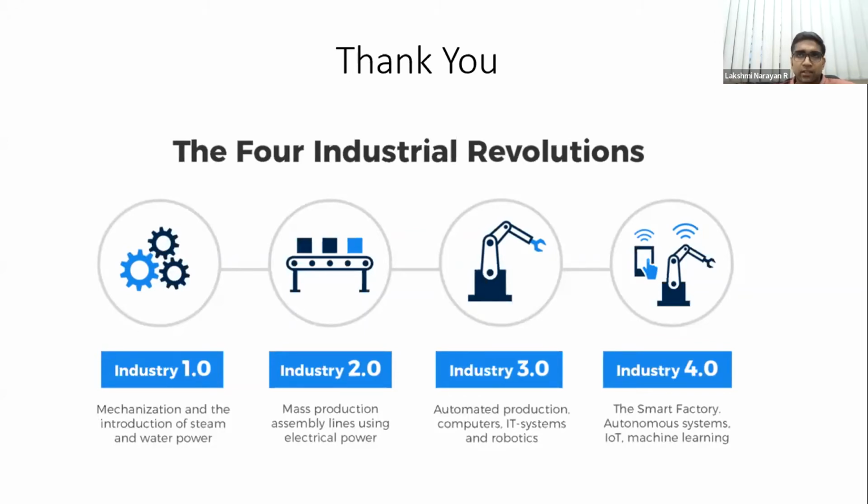This agglomeration can occur, and to prevent it, they make it as dry as possible. That's the best way. Or while mixing, they also try to inject a lot of steam so that the bed remains a little fluffy, just like how you puff in a lot of steam or air in some of these cereals so they become puffy. They gas with a lot of inert gases, pass them through, and keep the powder de-agglomerated. Otherwise, it can definitely occur. All of these attractive forces come in. A lot of fluid bed mechanics people are involved in those processes.